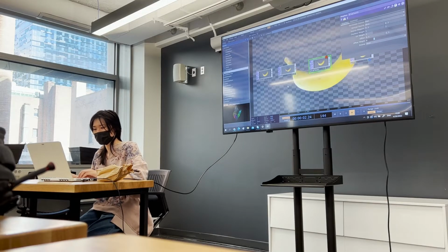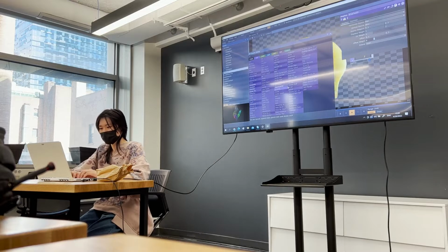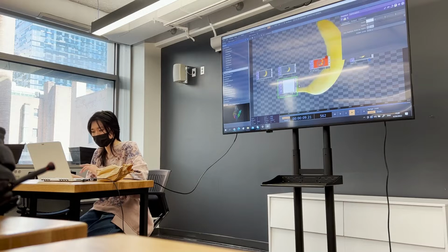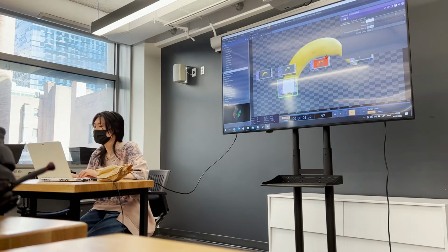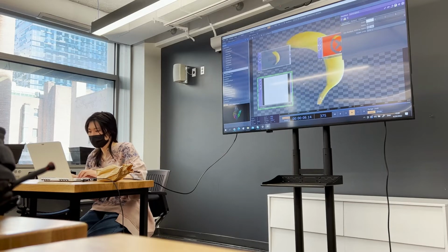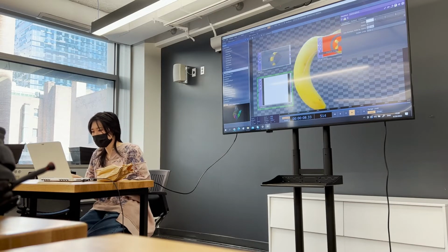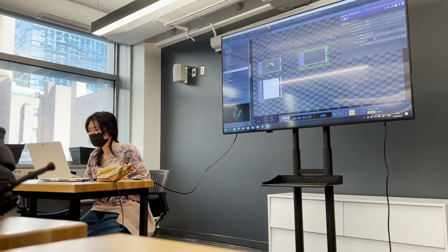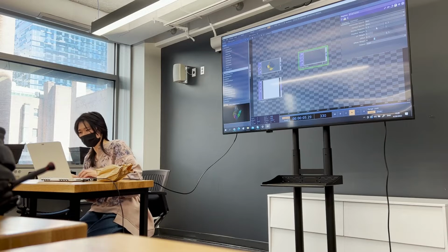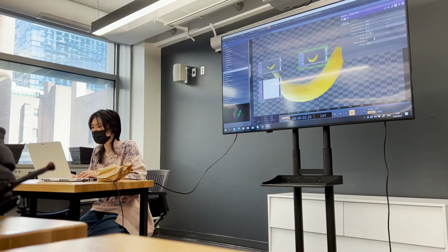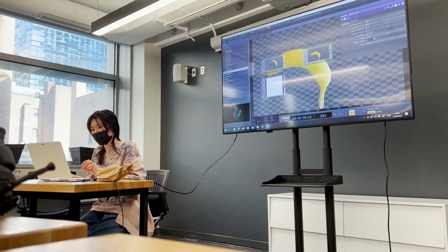So for example, I can drop a constant TOP, which is essentially a holder for a constant color. If you drag from the output and plug it in as the second input for the displace node, the banana's going to go away. The reason is that the displace weight is set too high. So if we change it to 0.1 and 0.1, the banana's going to come back.